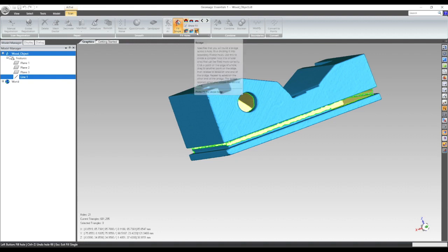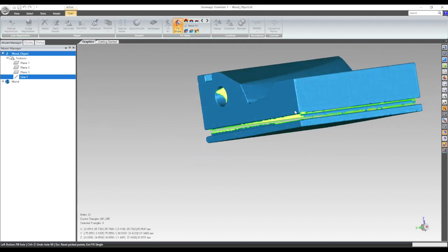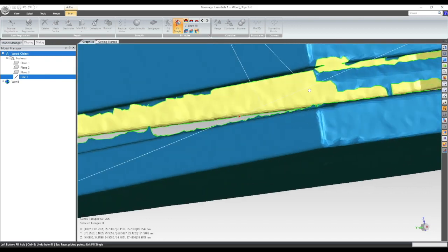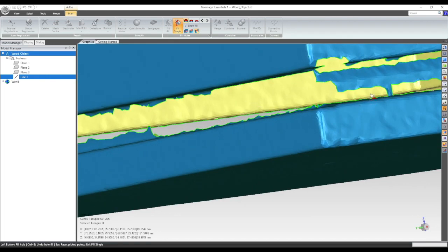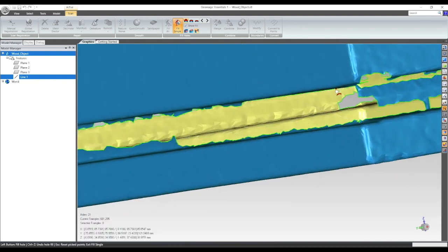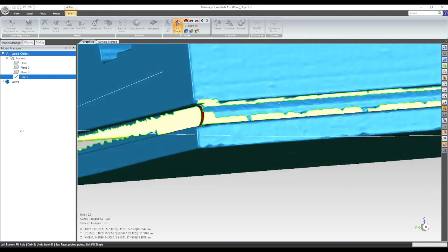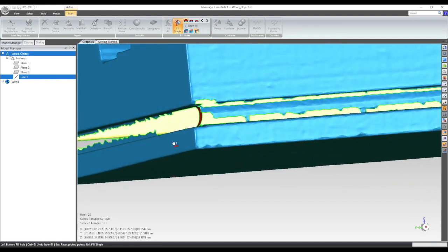Bridges are quite useful if it comes to regions, for example, like here, region that goes around the corner. So on that side I want to be flat, on that side I want to be flat, but I need first a section of it. So I click on it, hold the mouse button, pull it a bit, let the mouse button go, click it again, pull it, and here I have my bridge. So now I see, ooh, this is not what I really wanted. So I click Control and C, then it's back.